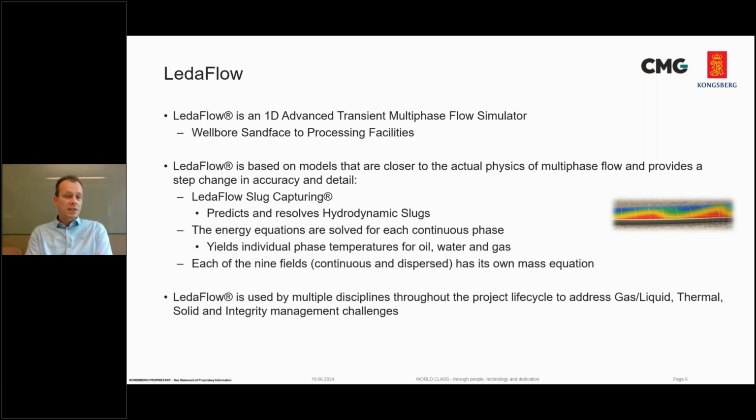The energy equations in LedaFlow are solved for each continuous phase. That means we have different temperatures for the oil, water, and gas phases. And each of the 9 fields, both the continuous as well as dispersed, has its own mass equation. So we're solving things like droplet entrainment, bubble entrainment, oil-water dispersion. We can solve that in great detail, and we have full control over all of those at the same time.